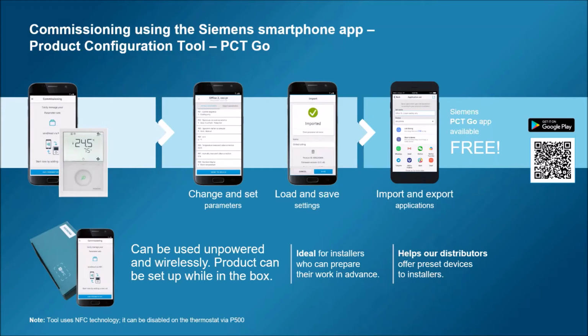There is a feature that is quite interesting in NFC. It doesn't need power. So you can do this while the thermostat is still in the box. So imagine you have a small plan, you will receive RDG200 devices. You can set them from your warehouse or from your office, preset with the app.